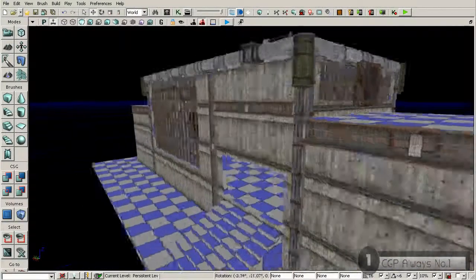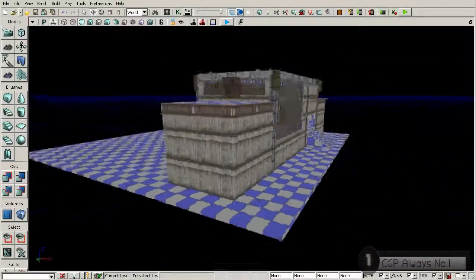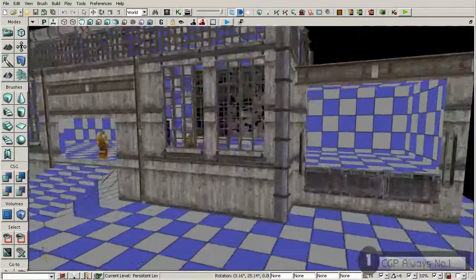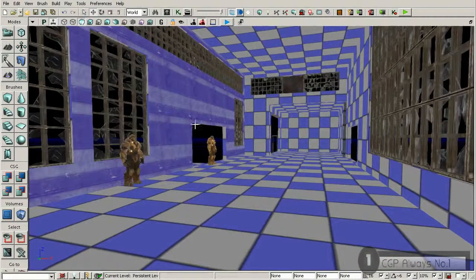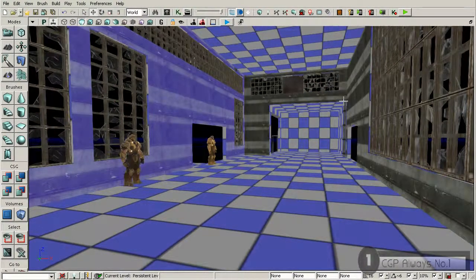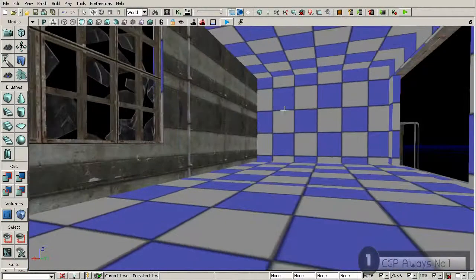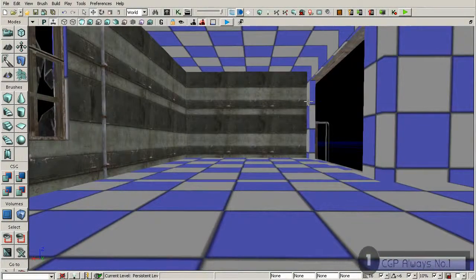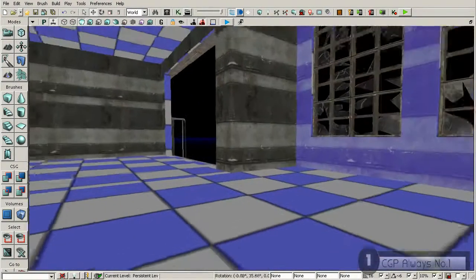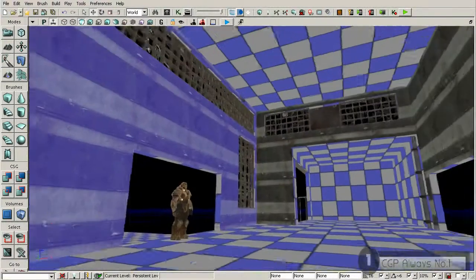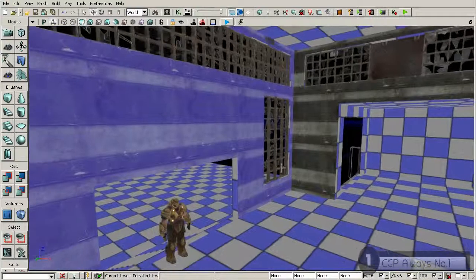With that applied, now I can come onto the inside here, hold down Alt, right click, and then Alt left click on the surfaces on the inside of my building. You'll want to do that on the interior here, because that's going to be the material that I'm going to be using on the interior, including the window sills and the door frames themselves. So you can hold down Alt and apply those as well.